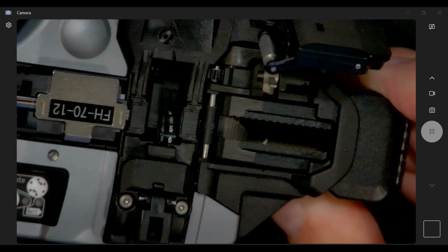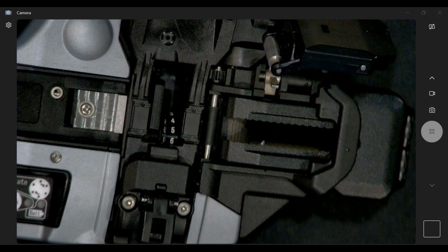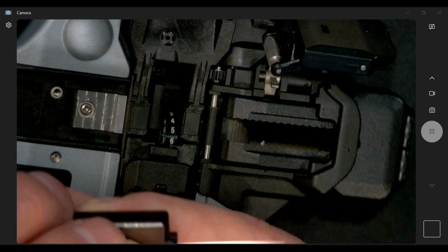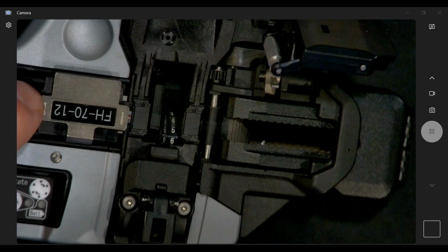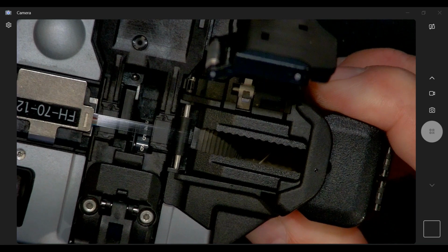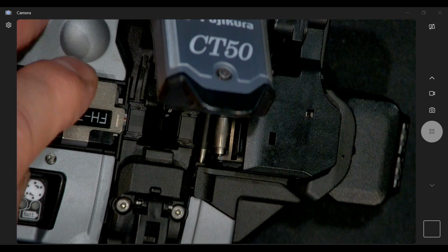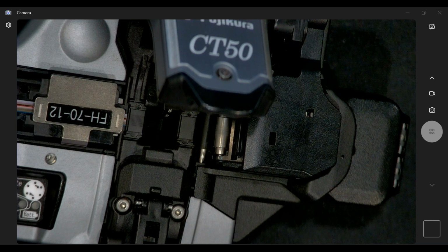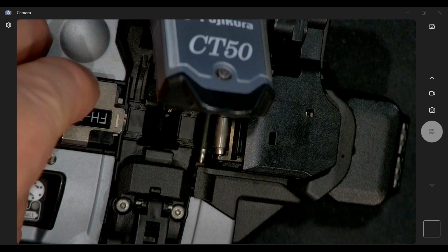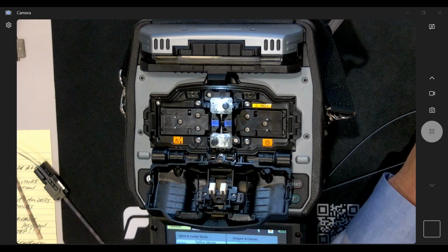So we're going to make a quick splice. I'm going to take this out. I'm going to put my 12 fiber ribbon array in on my fiber. You'll notice here how clean and balanced it is. Cleave the fiber. Now, if you can move over to the head position of the splicer. Can you drill down? Sure.